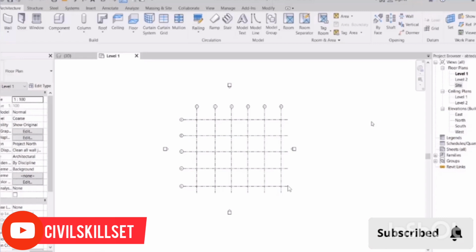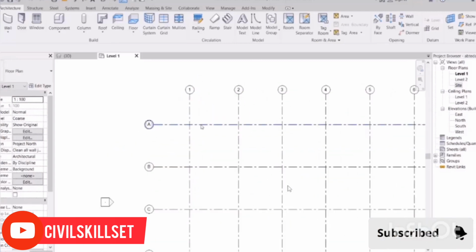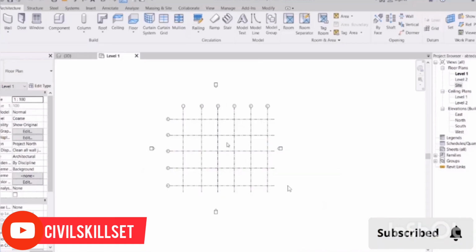Therefore, we can say that the structural file recognizes the 0 spot. But how? Just like I said, usually where 2 center lines are crossed is known to be the 0 spot of the project. So after drawing the grid, you're gonna have to choose where that is. For example, A and 1 or anywhere else. You're gonna move that spot into the 0 of the Revit and then start modeling.